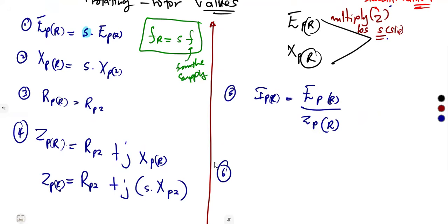Then another part is on the rotor copper loss. As we had before, remember the rotor copper loss. So we're going to also consider the rotor copper loss, 3 times I squared times R. So under the rotating values, we're going to have our current.